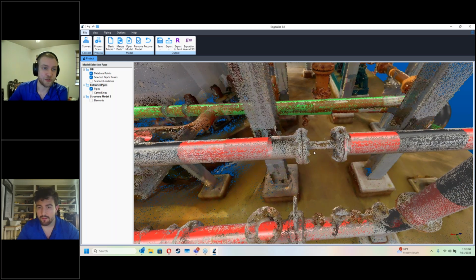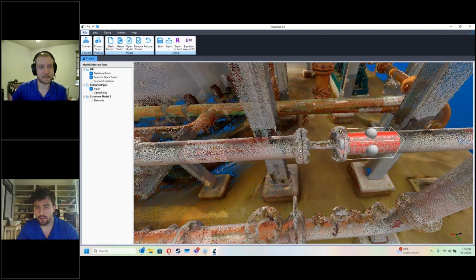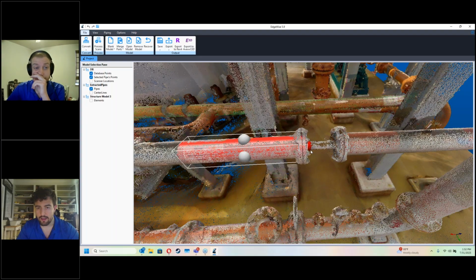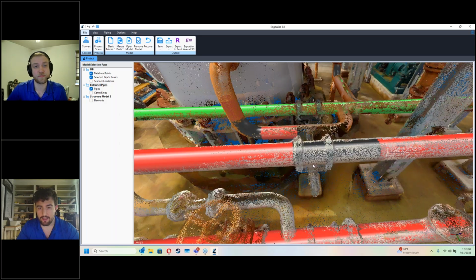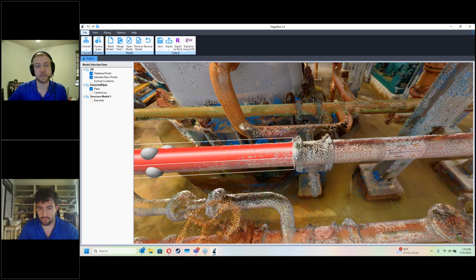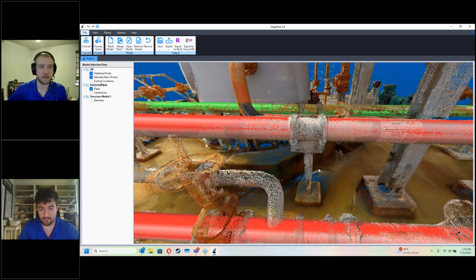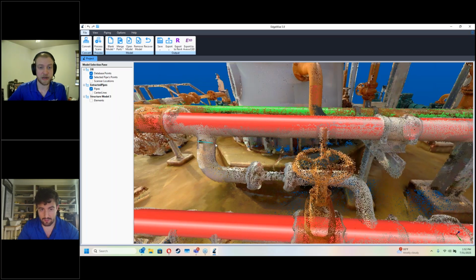But after you've done that, then switch the specs to whatever you prefer. That's similar in a lot of ways to Revit, in that Revit's more flexible. You can use any spec inside of EdgeWise. It'll go into Revit, but the geometry, the Revit family object, will be generic. It's going to be a generic pipe, and you'll need to switch the families over inside of Revit.